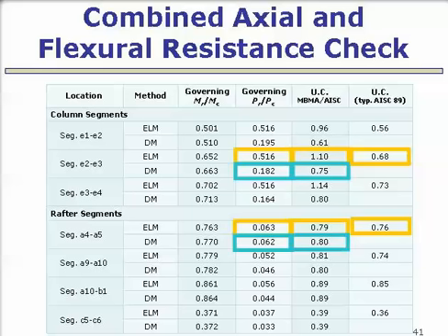Now, to compare a few different numbers out of the different calculations, if we look at that particular segment and consider the effective length method boxed in gold there, what actually happens is when you do the proper effective length method calculations, this frame has a lot of leaning columns in it.